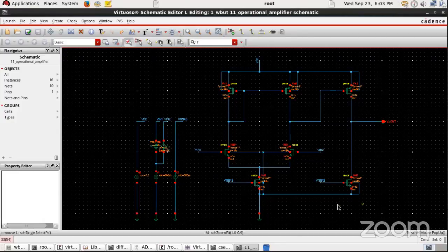It is not a benefit. See, you have already built a differential amplifier, and you have a common source amplifier. So you are building an operational amplifier using the differential stage and the gain stage. The common source amplifier is also called a gain stage amplifier. I got it. So the output signal from the differential stage will be amplified by this common source stage, exactly.